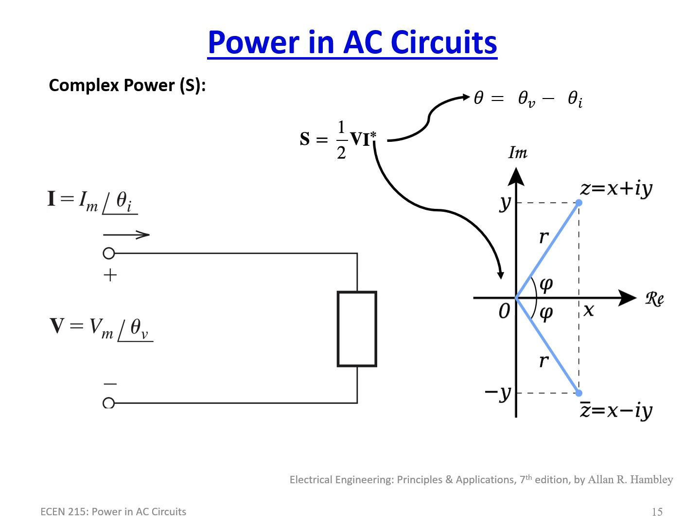Probably a long explanation, and you might not have had that question, but it's come up a few times. Why are we doing this? So that's why we have the complex conjugate there. What you need to know to be able to solve this is, if you're given what is the complex power, like what is the true vector of the power, you just take 1/2 times V times I conjugate, and you've got your answer.